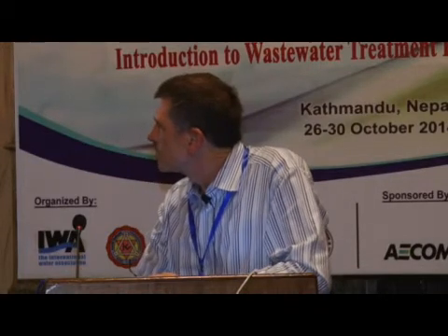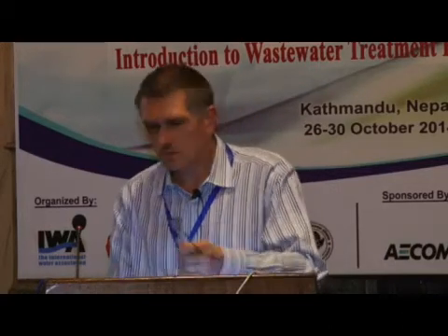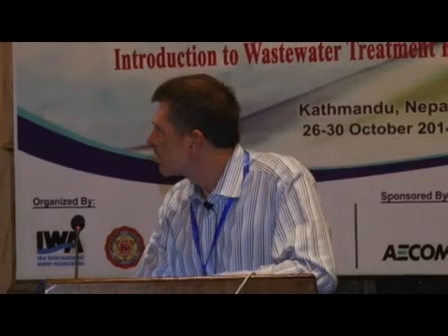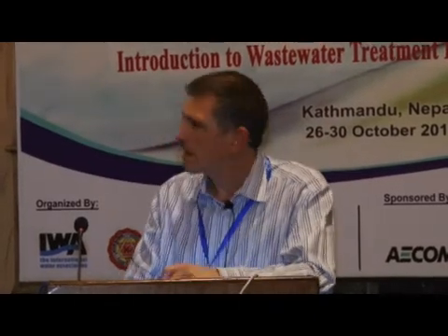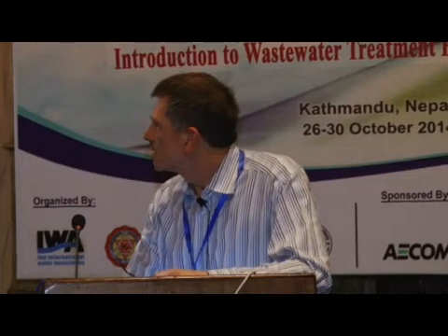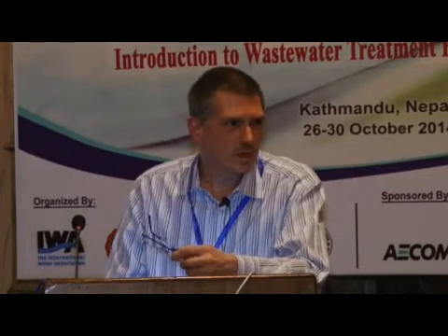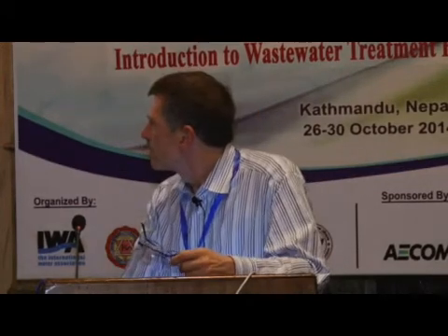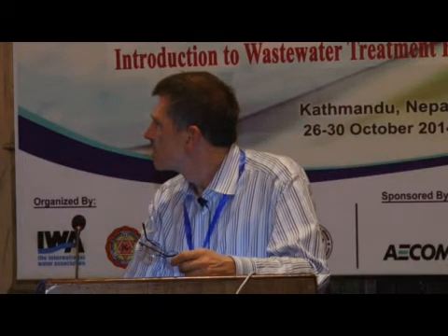So we see our COD, which is of course really high in the reactors because you have sludge in there. You measure total COD, so it's not an important number, but effluent is 35 with COD. TSS is 10 because of the simple model. VSS 7.6 in the effluent.